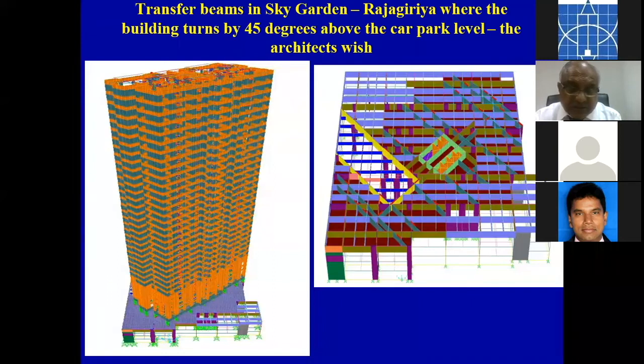So with all this, what have you done? You have increased the factor of safety in this particular member to about 3. Instead of 2, now the factor of safety is about 3. What are the chances of such a member developing cracks and undergoing corrosion? You will say the chances are much lower. Why? Stresses are much lower. If the stresses are lower, the chances for cracking will be low. So basically, you can see designing a building does not mean getting numbers from software and then finding the reinforcement. Again, you have to look at how the building is going to behave short term and long term.